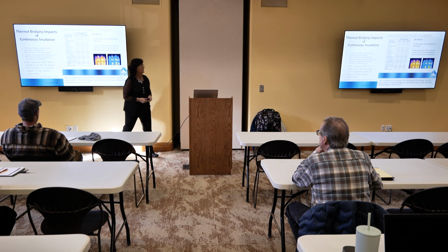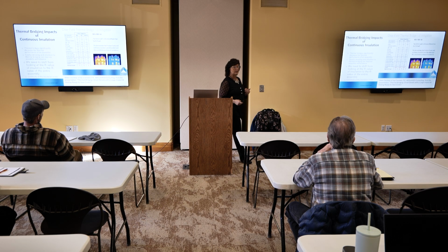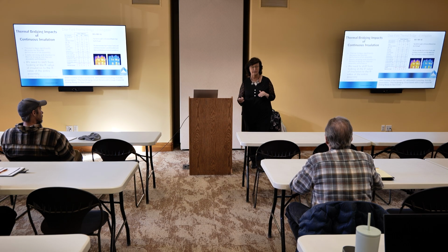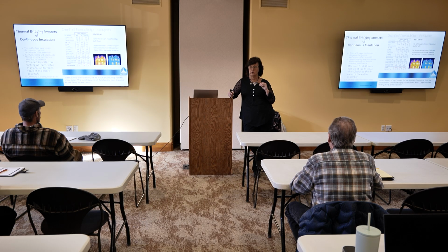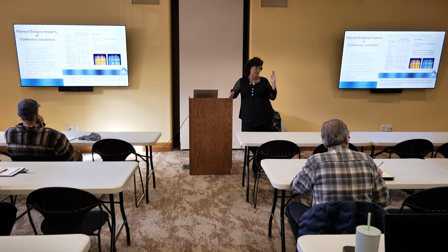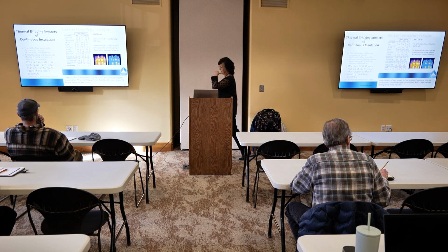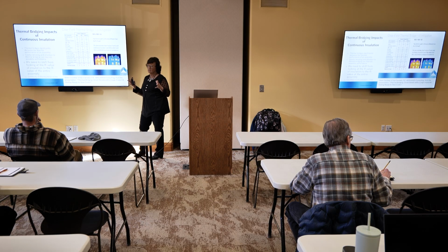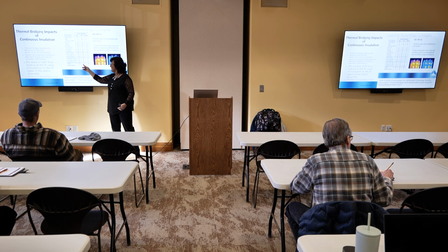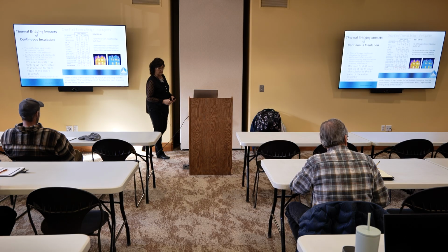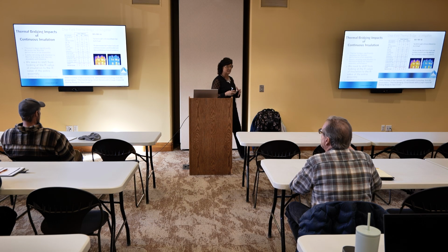So you see, the code will start going more and more that way. In fact, it has started in 24, trying to get you to think about your walls, or any of your assemblies, as U factor and not R value. It wants you to think not just about the insulation you put in it, but all the layers: the sheetrock, the air film, the studs, whether metal or wood, whether 16 inches on center or 24 inches on center. All of those make a difference in the overall total R value or U factor of the wall. I want you to start thinking of things as an assembly.